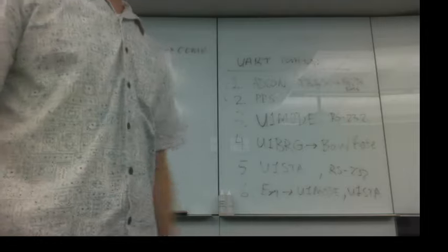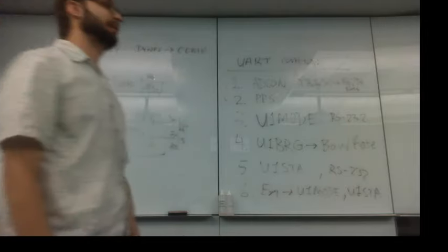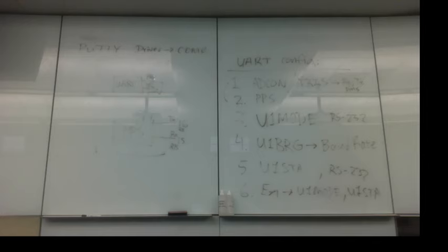So the baud rates, in the manual they give you these equations for what do you write to the baud rate generator register to get the baud rate that you want. One of the equations shows the actual baud rate that you get when you have a certain value. That value is going to be an integer. So when you write that integer to the BRG register, then you get that baud rate. And then it shows you the closest you can get with a specific baud rate. You round it to the nearest integer, and that'll show you the error.